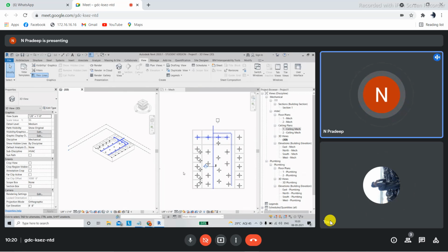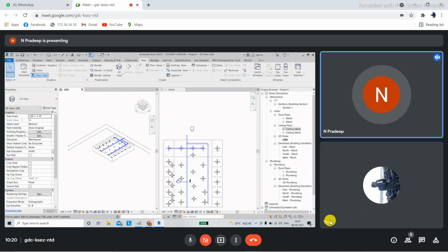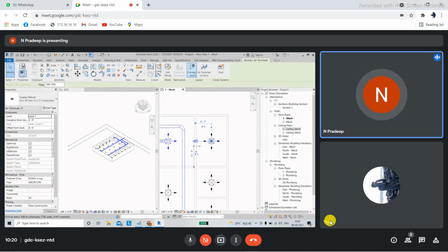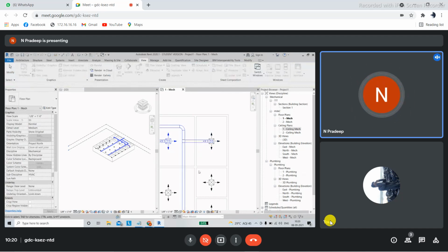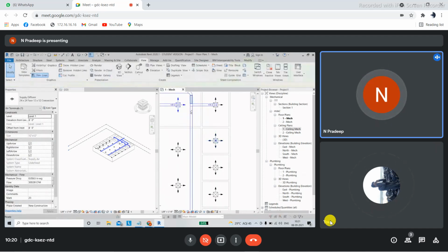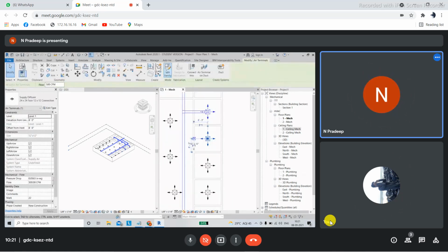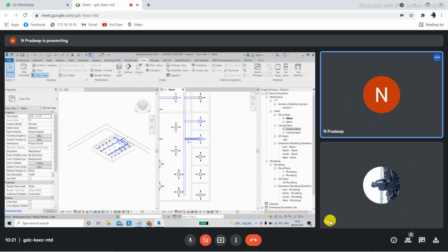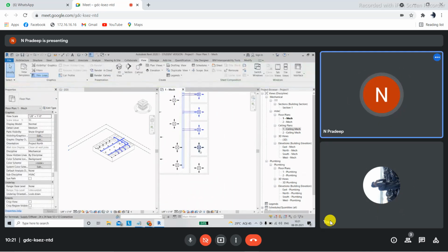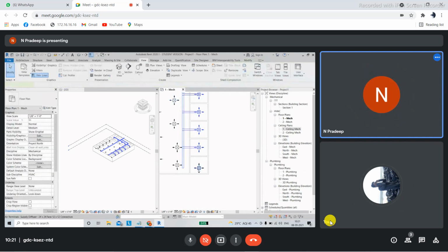Okay. Next thing, I'm going to connect all the ducts. Now we have to patiently select all the duct diffusers individually like this, and then go to this Layout panel, Connect Into, and connect it with the duct. We have to do this individually only. You can't copy all the duct diffusers and connect them in a single step. So you individually select all the diffusers, and then connect everything into this particular duct.